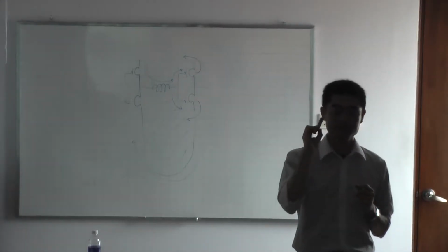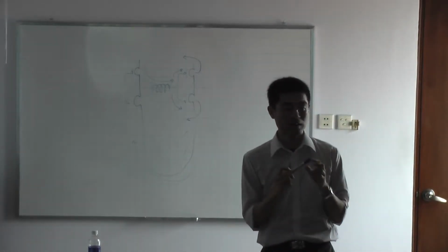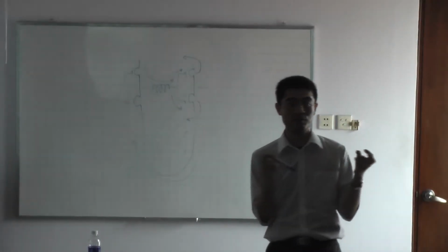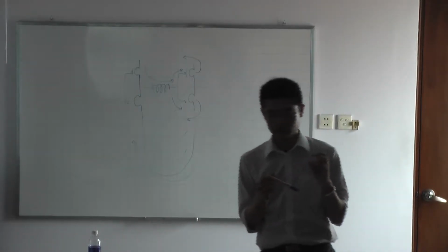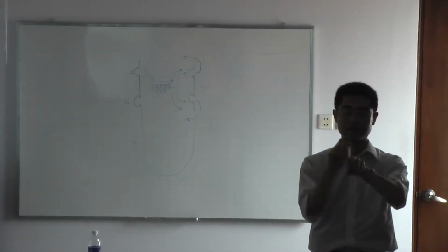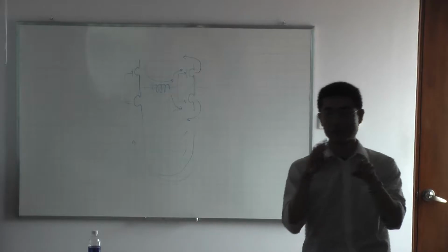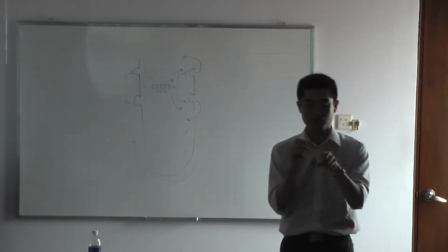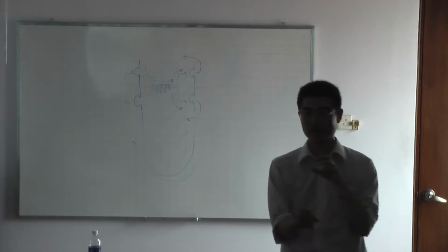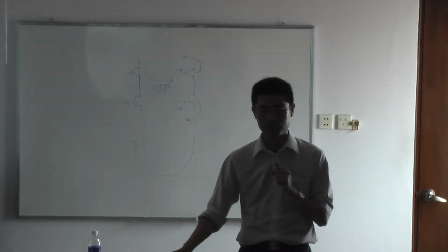An attenuator will attenuate the input signal. So 20 dB attenuation means the voltage becomes 1/10, and 6 dB means the voltage becomes 1/2. The point of the attenuator is that the input impedance of the attenuator should be 50 ohm, but the output voltage is lower, for example, half for a 6 dB attenuator. So the input impedance always stays 50 ohm, and it will have attenuation. Actually, the attenuator is just a resistance ladder, like shown in the slide.